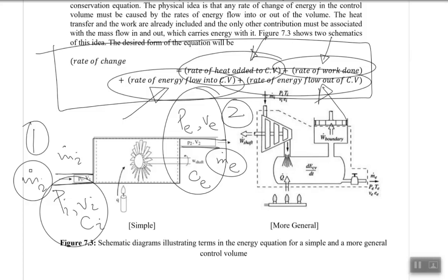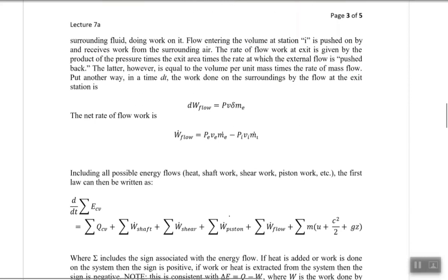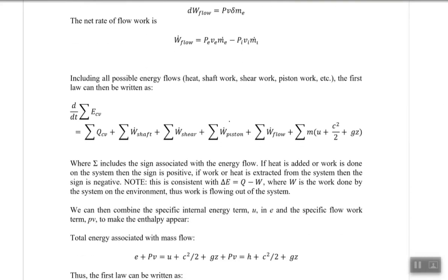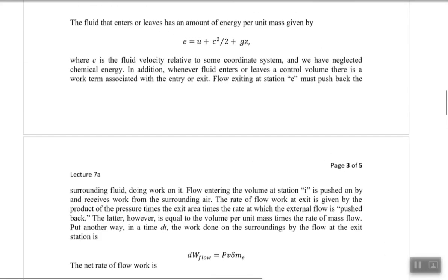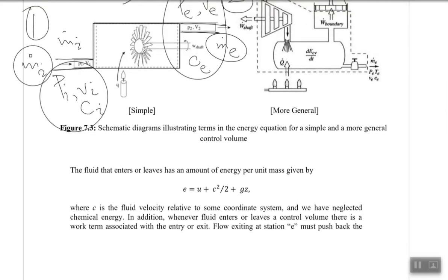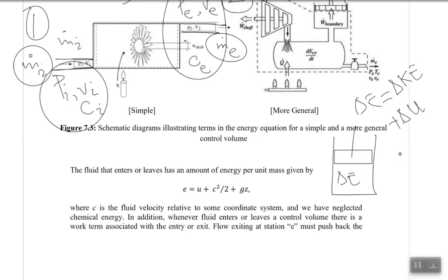So in other words, if I'm combining this, that would be something like this. So there would be total energy, heat energy, work energy, and the energy, but we will come back to it later. Now what would be the energy which is entering with the mass itself? Remember, in our first law of thermodynamics for the controlled mass system, we did say the energy which was changing was equal to the kinetic energy change, the internal energy change, and the potential energy change. We were ignoring the chemical energy, magnetic energy, and so on and so forth.